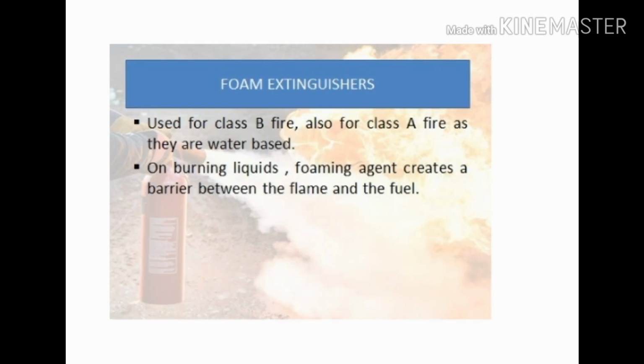Foam extinguishers are used for Class B fire, and also for Class A fire, as they are water based. On burning liquids, the foaming agent creates a barrier between the flame and the fuel.